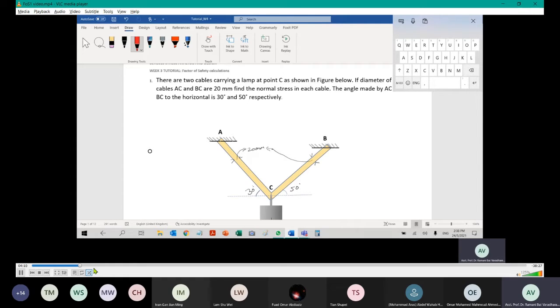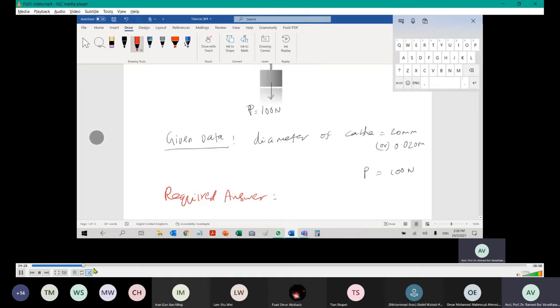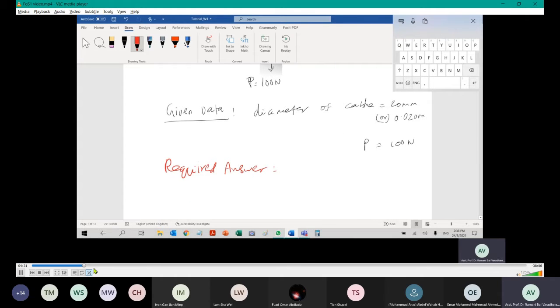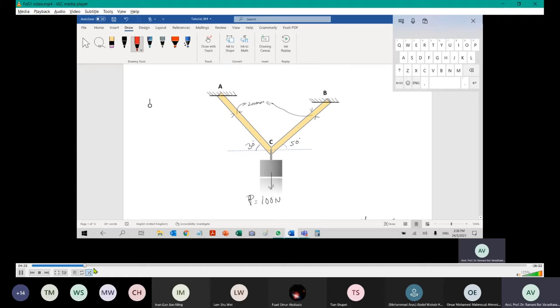There is no way it gets shear in this situation. If the weight of the load is increased and overcomes the stress the member can withstand, it will extend. So it is a normal stress in tension, which you can also call tensile stress.